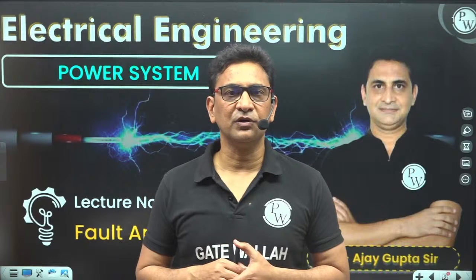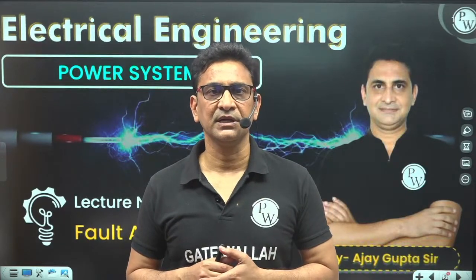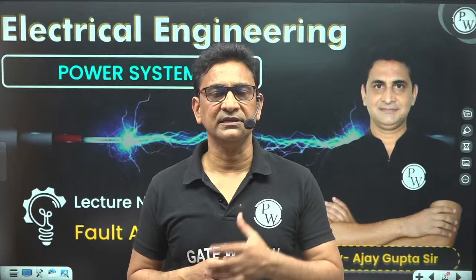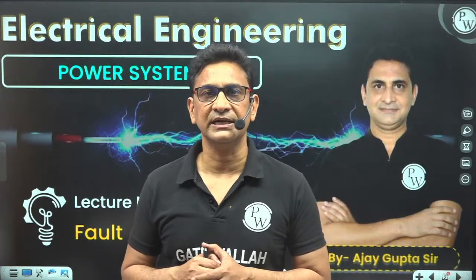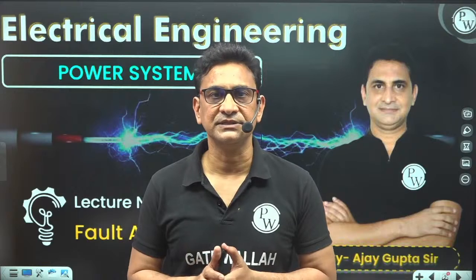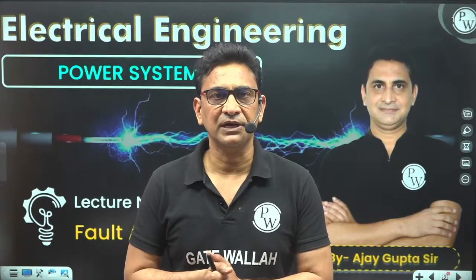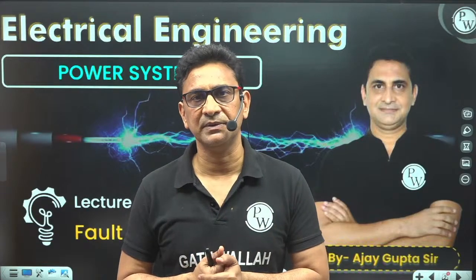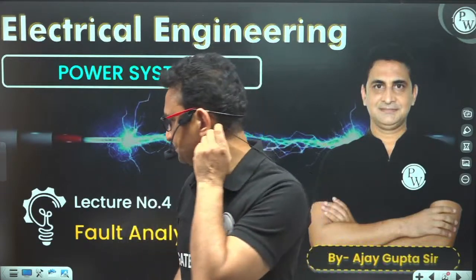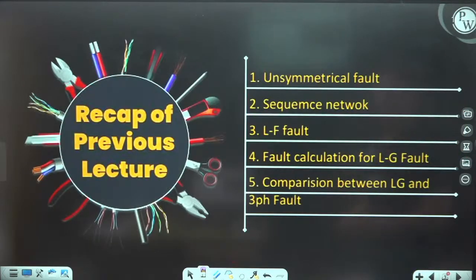Whenever a line to ground fault occurs, the positive sequence network, negative sequence network and zero sequence network are connected in series with a 3ZF impedance, where ZF is the fault impedance. In this way you can find the value of fault current, which was 3E divided by Z1 plus Z2 plus Z0. So let's move to the line to ground fault further.